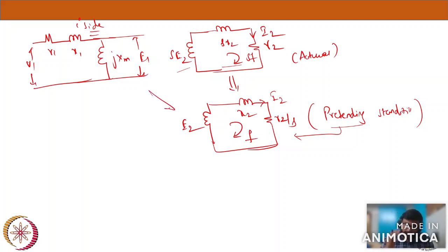But what is the reason behind doing that? To know it is very important and it's very interesting. That's why we discussed this. So whatever might be the parameters of my rotor circuit, if at all I can make the same amount of current flow in the rotor, my stator can't distinguish what kind of motor this is, as long as my rotor field is rotating at the same speed.